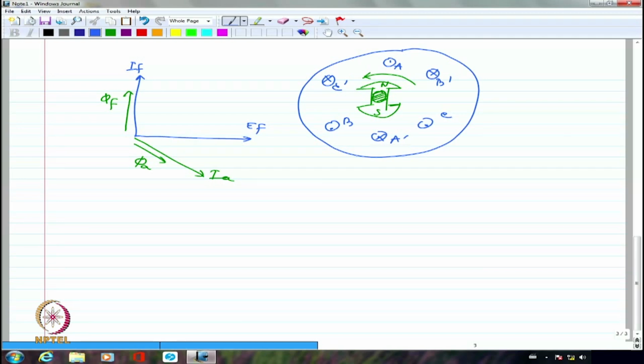Another portion I am showing as XAR or XM, which is the induced EMF due to the armature currents, which I call armature reaction, or armature flux based induced EMF. So these two together make up, and I am showing that as a drop because of what Tanay asked just now: you can't have, even at unity power factor or whatever, further and further addition of voltage.